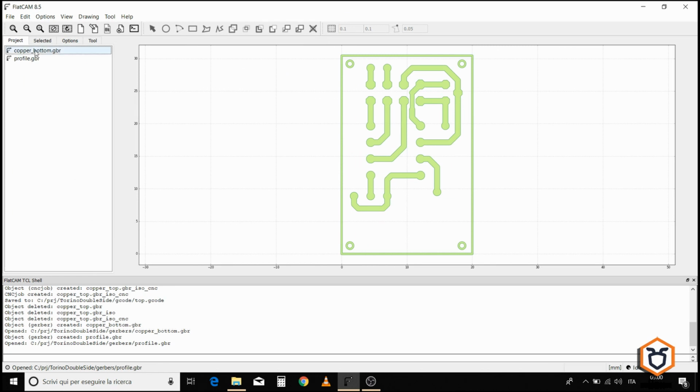When you execute a double-sided machining, you have to take in account that, if the Gerber has not been mirrored, it is necessary to modify the orientation of the bottom side, mirroring it respect to the one generated from the CAM processor of the CAD, used to generate the corresponding Gerber. We strongly discourage you from mirroring the Gerber instead of mirroring the working geometry.